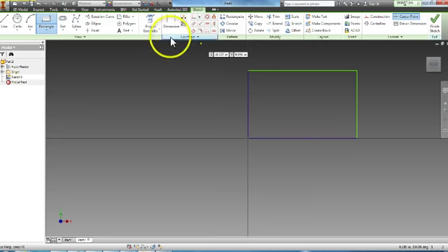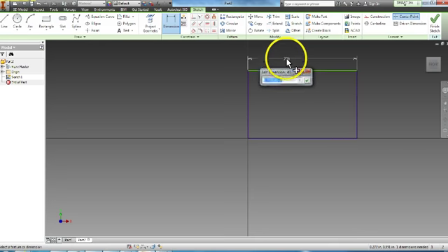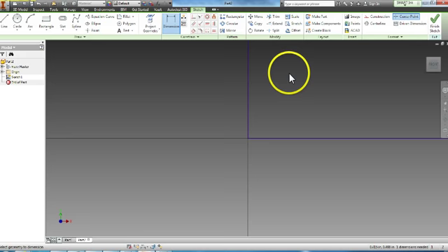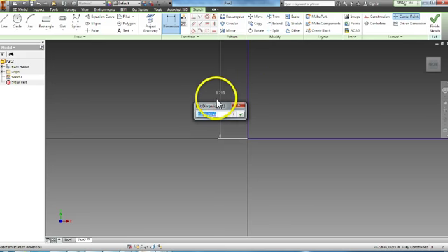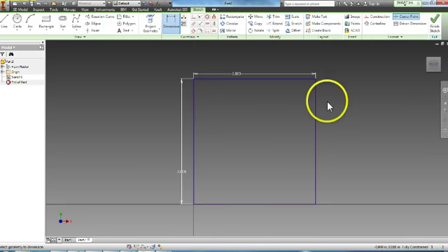I'm going to sketch it, now I'm going to constrain it by going to the dimension tool. When I click dimension, I'm going to select the side and the size of it. In this case, I want it to be 2 inches, and then green check mark. I'm also going to tell this side the size. I want that to be 2 inches. I'm going to use my view cube to zoom out. Now I can see I have a 2 inch by 2 inch square.